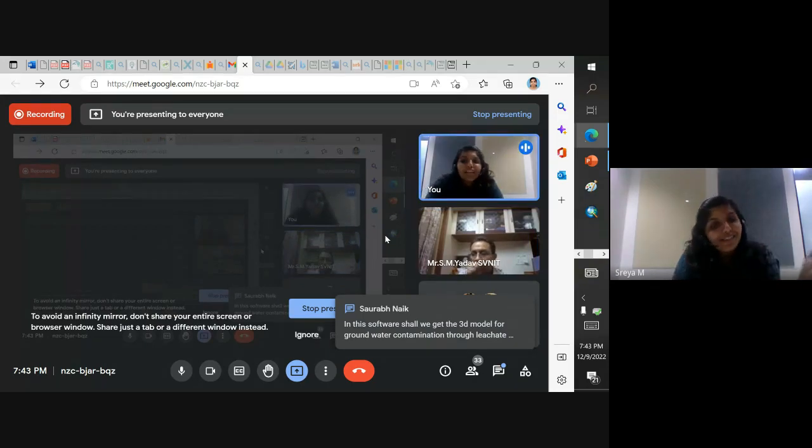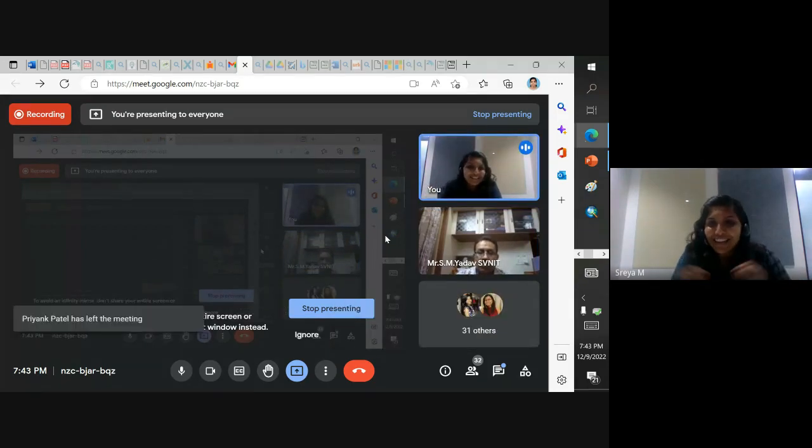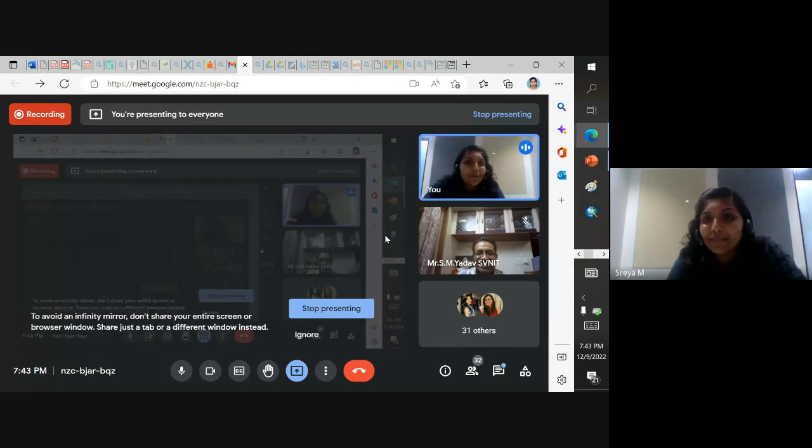This is a question I always get whenever I go for any training, so I am used to answering it. Usually, we use MIKE SHE for shallow aquifer regions. MIKE SHE can accommodate both your surface and groundwater interactions, and also your shallow aquifers.